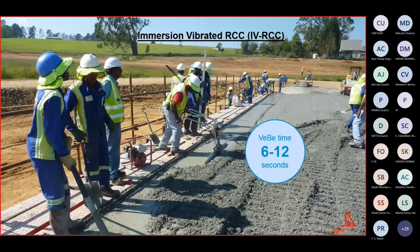Immersion vibration is achieved without adding any grout and whilst the RCC is still fresh. The use of the set retarder helps also on this task. This is called immersion vibrated RCC, the most simple and efficient way of building modern RCC dams and its interfaces either against formwork, rock abutment, embedded elements, or dam instruments.